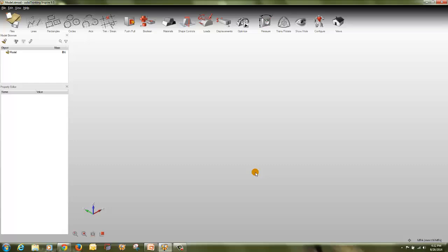with the mouse. Pulling a face with rounds. When you pull a face that has rounds adjacent to it, the rounds are moved with the face. Sometimes complex rounds and blends will prevent a face from moving because they can't be constrained at the desired position if the face is moved. If you don't care about retaining the rounds, you can often free up a stuck face by pulling out the rounds with the push-pull face tools until it becomes a sharp corner.